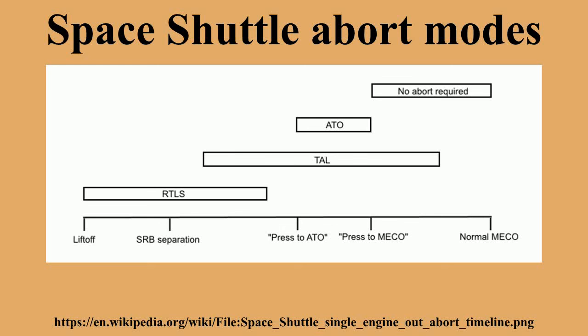In an ATO situation, the spacecraft commander rotated the cockpit abort mode switch to the ATO position and depressed the abort push button. This initiated the flight control software routines which handled the abort. In the event of a loss of communications, the spacecraft commander could have made the abort decision and taken action independently.